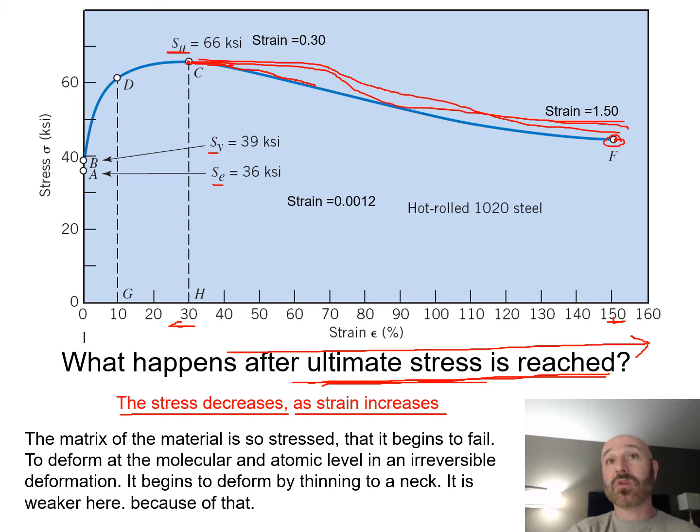It might be slowly creeping down over time as you add more and more stress to it until it fails on you. Maybe you don't want that to fail. Maybe when you're designing your product, you only want it to never go above a stress over here, so you never even get to your yield strength. Maybe you always want to stay in your elastic region. Those are things to think about: what these values actually mean, not just pulling them off a chart and saying, oh yeah, no problem, I'm nowhere near that with mine. Well, maybe not.